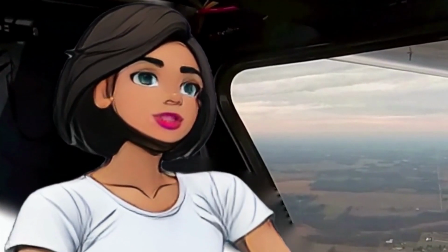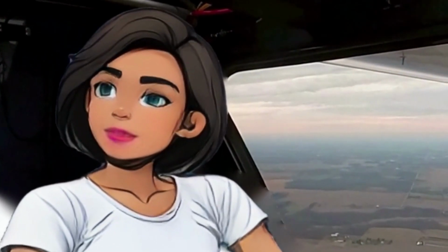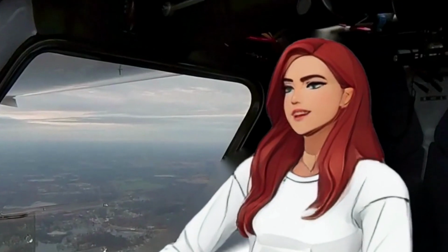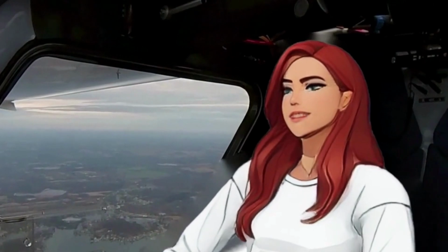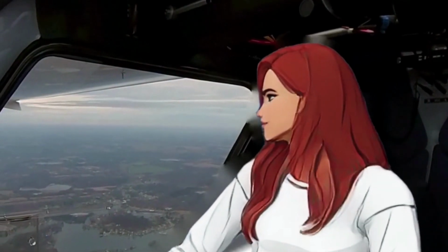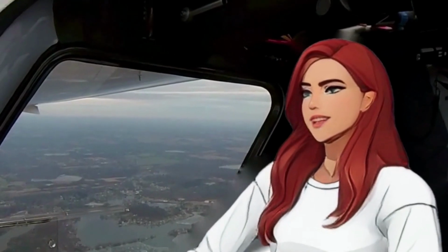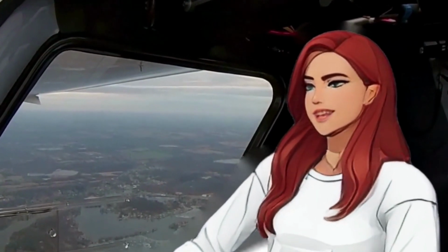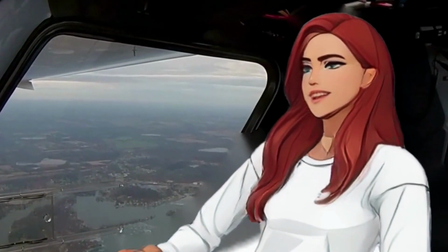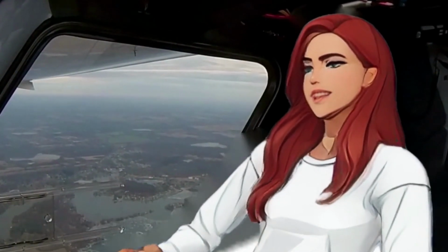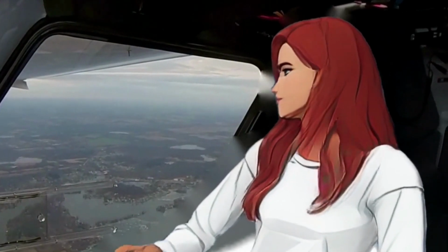When I look at that drawing, it looks like I could just use the elevator to control airspeed and use the ailerons to control rate of turn. Why do I need to worry about airplane attitude? When you move the elevator, it takes some time for the pitch attitude to change. Then it takes some more time for the airspeed to start changing. This delay between your action and its effect causes you to over-control. It works much better to decide how much you should change the pitch attitude and move the elevators accordingly. Then, after the airspeed has stabilized, make another correction if necessary.